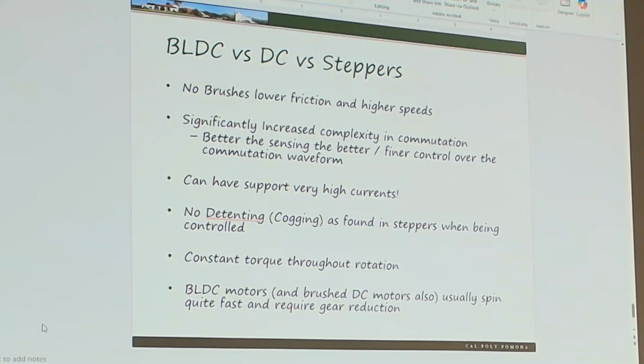The DC servo motors, it's kind of a nice, so it's a DC motor with feedback in position, right? That's kind of a happy point between the two. Yes, you have a holding torque, but it's modulated as a function of the load demand based on the PID. So it's not always. You can servo a BLDC for position and or velocity, because at that point you're just controlling the motion. You don't care how that motion is generated. The BLDC driver is doing that for you.